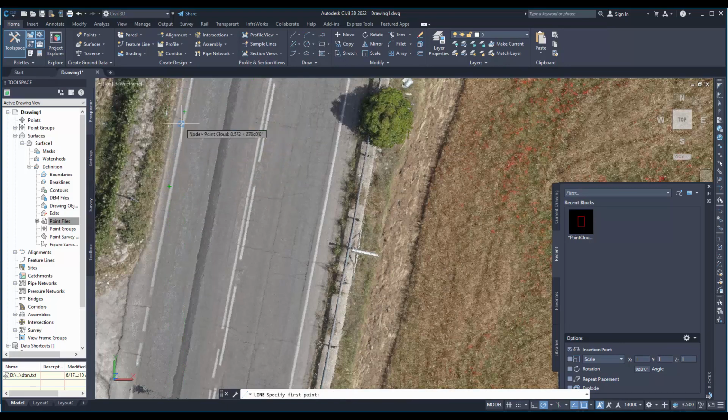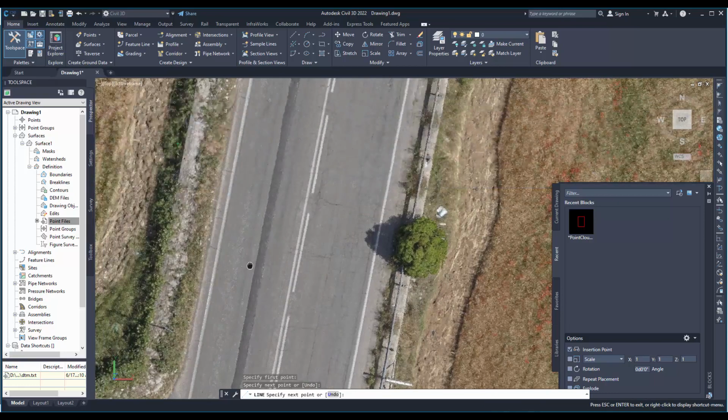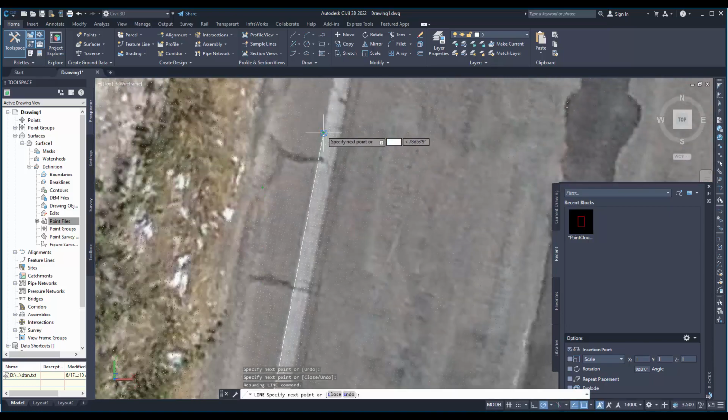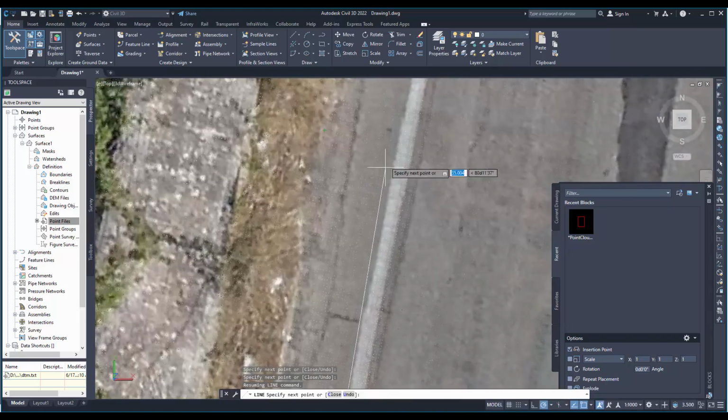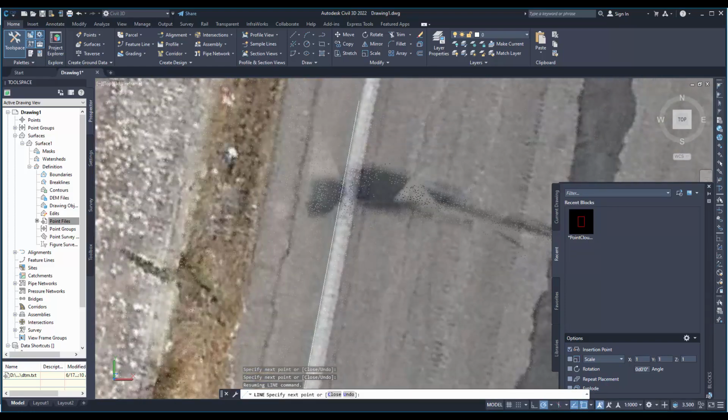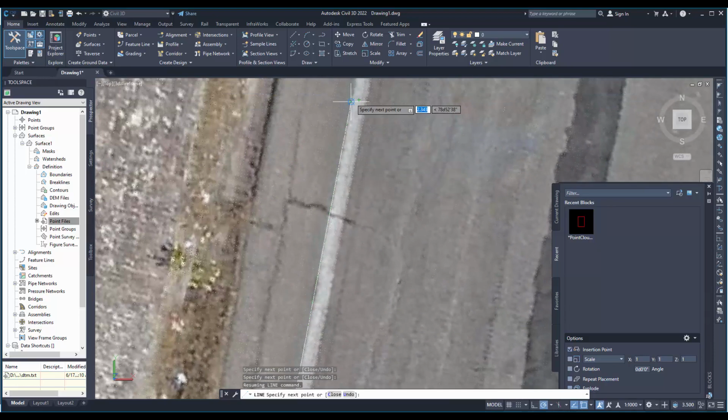So you see that the new point here will also have an altitude of 34 point, let's say 78 meters. So of course for production we would zoom in more. Now we are able to see the points. So this is then one way of how we could draw the survey map in 3D.